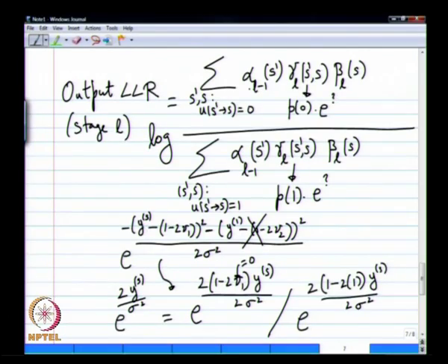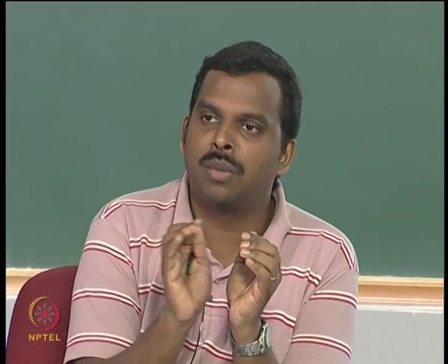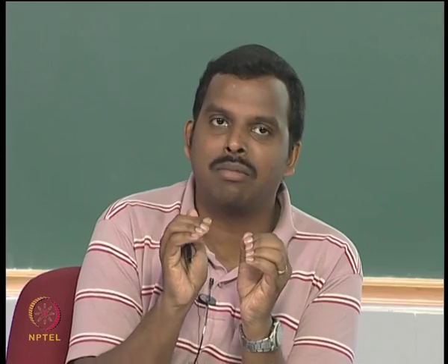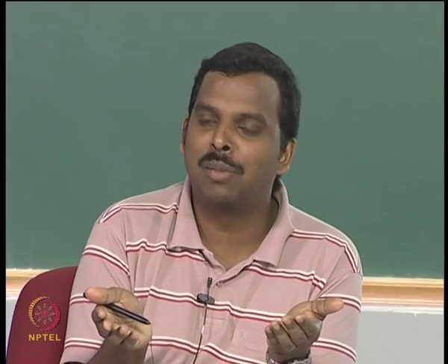Of course, not just the extrinsic, even the ys that you received for L minus 1 will feed into this, all that you do not subtract, that you use, but in the Lth stage explicitly you subtract what is coming through. If you think about it, that is an approximation in your iterations. There is some dependency that will carry through, you are not really subtracting all the dependency, but if you account for all of that then your decoder becomes optimal.